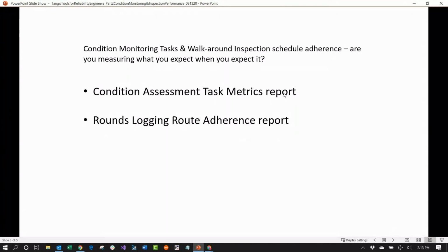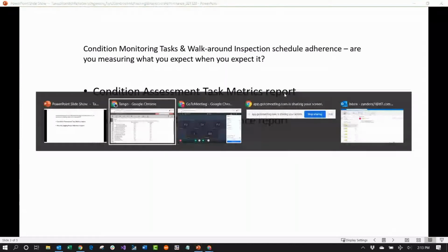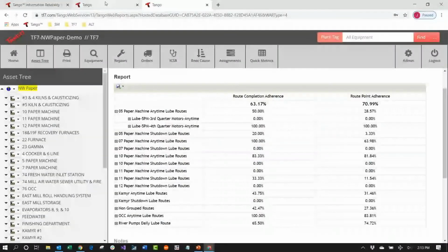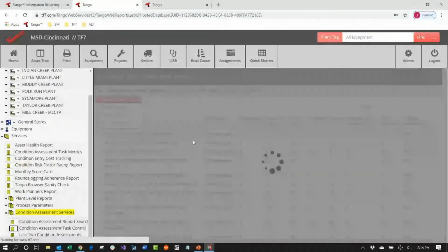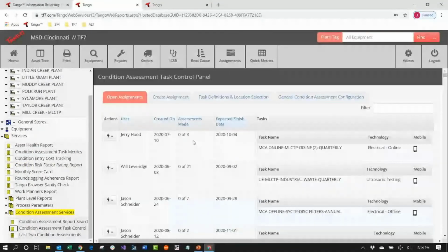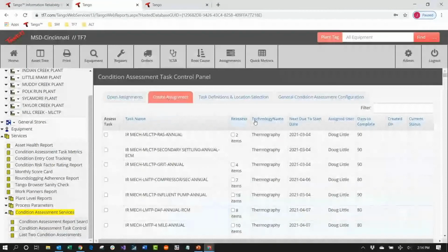Okay. And another thing, reassessments, is another tool. If you complete a task, if you have a 30-day task, reassessments aren't real valuable to you because you're probably going to redo that task fairly quickly. But let's say I have a quarterly or semi-annual or annual task, and I'm committed that I want to get everything on that task during, let's say, every 180 days, but the first time I'm out, I only get half of what's on the task. Tango builds what's called a reassessment task with everything that's in alarm and everything that's missed, and you can now redo the reassessment task the next time. Let's say you get half of that again, so now you're at 3/4 of the initial task with 25% hanging out. Another reassessment task is built, and you keep whittling that down until you get the complete task done.